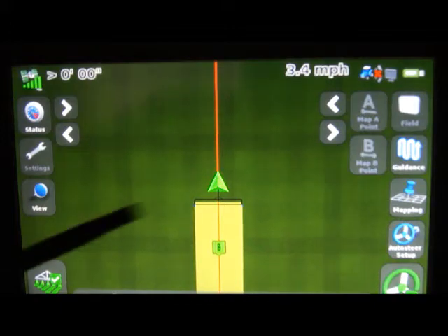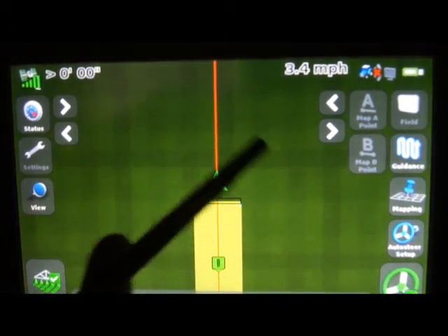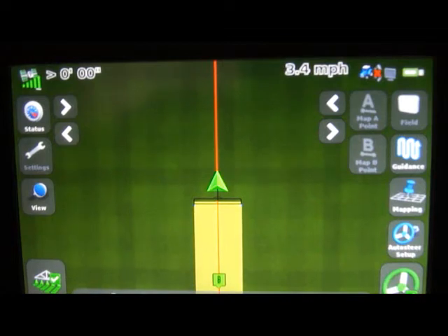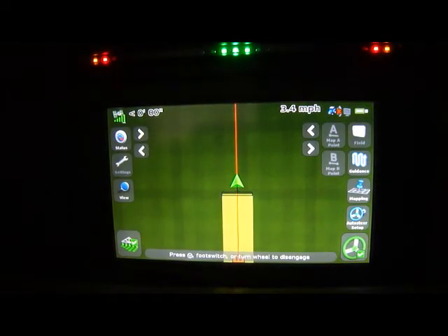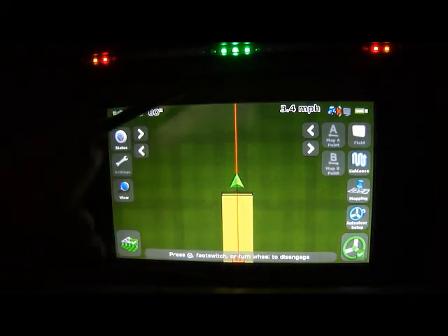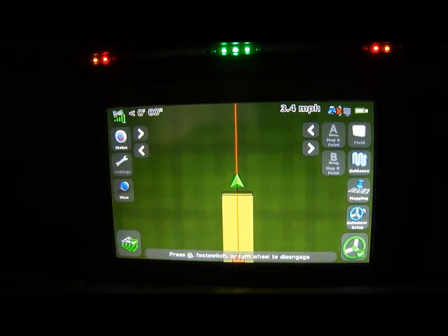You will see now that we've run an AB line that our LED lights light up across the top of the screen. Looking at the screen across the top, you can see the LED lights. That is your light bar system, and you can remember we set our LED distance, meaning one red light represents 12 inches.